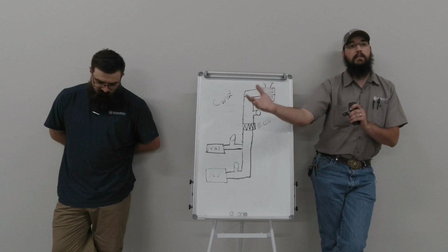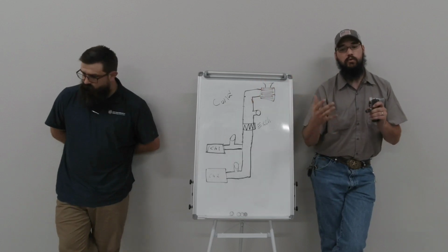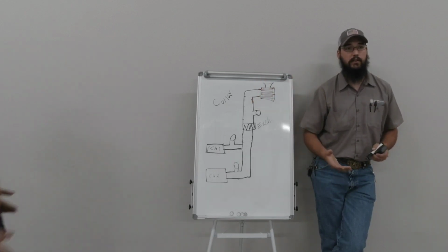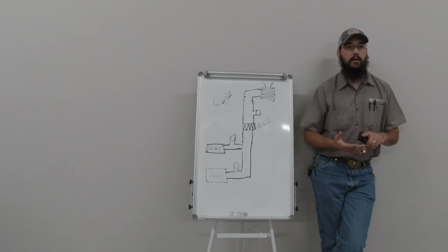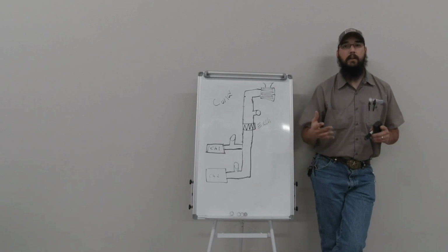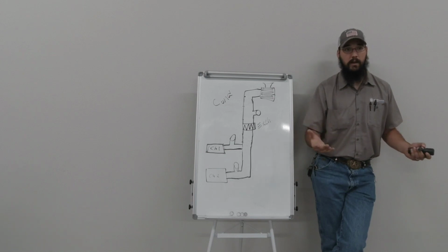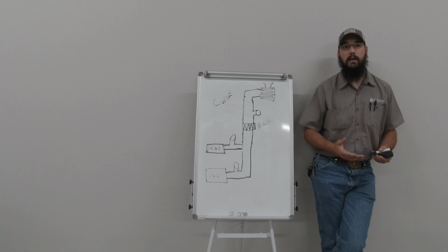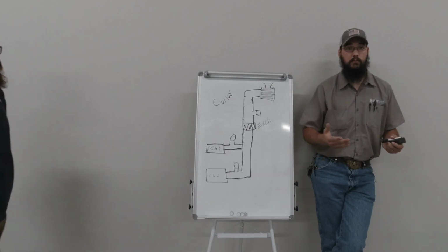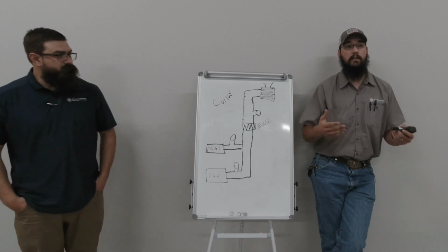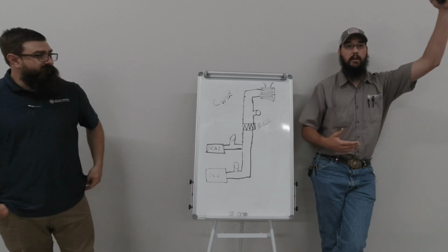So that end of the system ends up taking a huge punch in the face and just wear and tear, energy cost, everything, that it doesn't need to. On top of that, where normally the building might do fine on one pump, if the system is balanced wrong, it might take 2 pumps on an improperly balanced system to maintain enough flow to even keep flow on some of the upper floors.